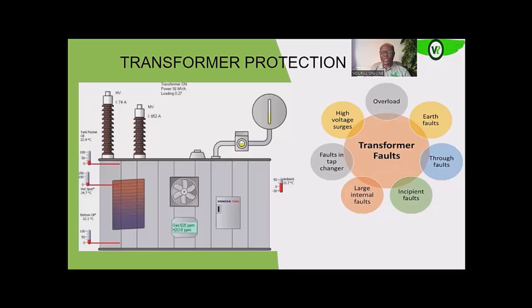Once there are problems, they will protect the transformer against such internal faults, like the differential protection system, which looks at the current flowing through each of the phases and compares them. Once there is a short, or an excess, or a short of a particular phase to ground, or within that particular phase winding, the differential protection system will trip and protect our transformer against such faults.